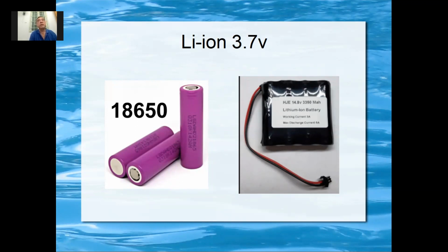When one battery is full, the other battery is not full, then you get into problems. The one that is full, if you continue to charge, you can damage the battery, and the one that is not full cannot be charged. So you need a balancer, where the electronics will bypass the battery that is already fully charged, and then go on to charge the subsequent ones.